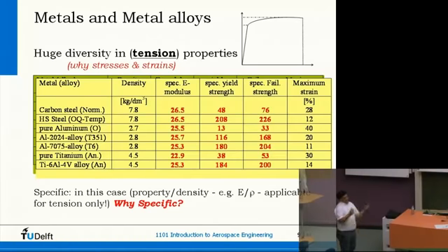So now if I have to design a structure, I will not only look at these specific properties, but also look, for instance, at thicknesses. If I need a specific force and this ends up with a thickness of 0.3 millimeter, that's very thin. So that will be very vulnerable, for instance, by handling or also by impact. Aluminum probably will be about 1 millimeter if you compare it. Titanium maybe 0.6, 0.7. That's much more rigid, much more sturdy to impact and these kind of things.